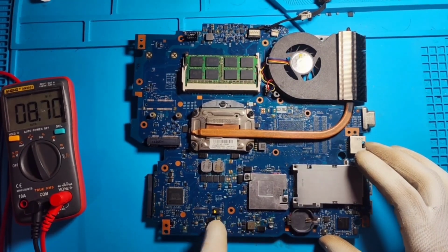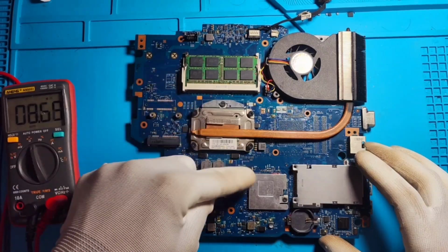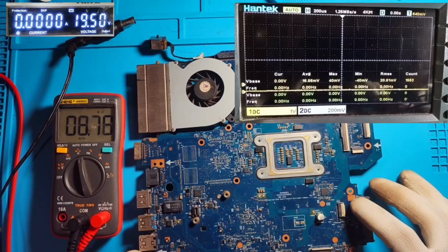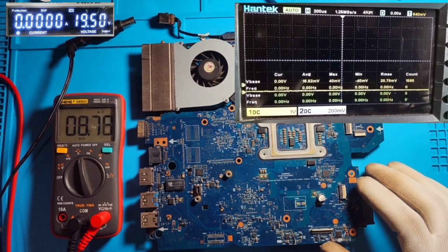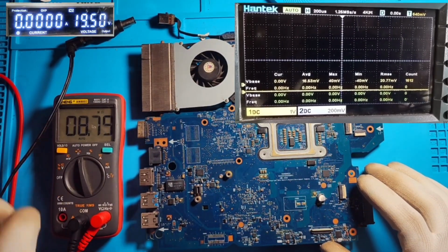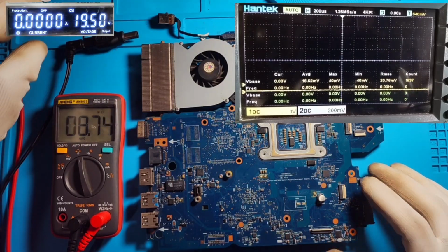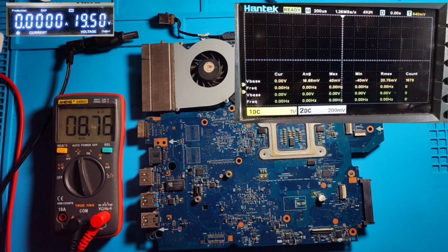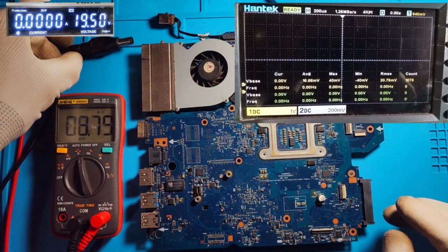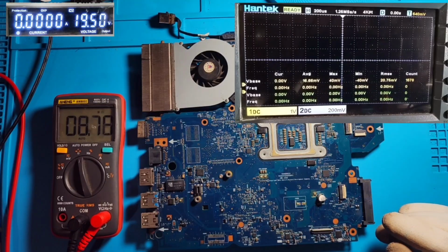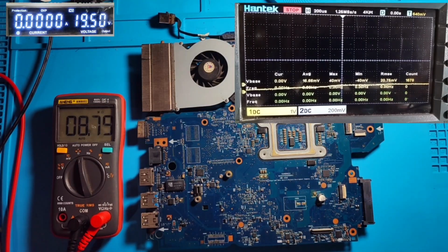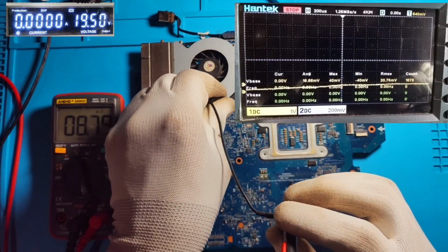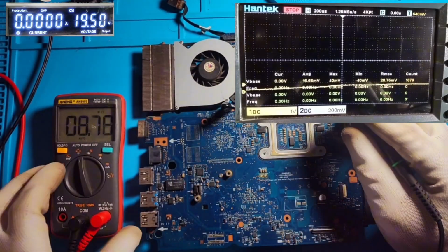So in order to check this, I will check with the oscilloscope if there is any fluctuation in these coils. Okay, now you are able to see on the display both the screen of the oscilloscope and the power supply. Now I am going to check with the oscilloscope with the single-sequence function set. I am going to use the trigger function in order to identify the first sequence of the voltage rise, so that I can detect if there is any fault in the regulator side.